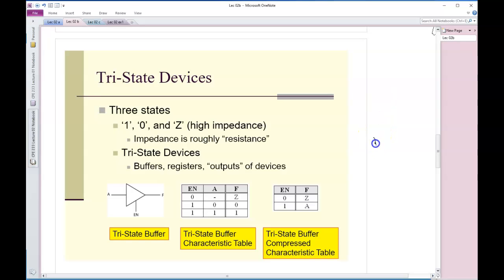So what we have is V equals IR, right? I know people have worked with resistance and impedance probably in your circuits courses, but if I switch this around, R equals V over I. High impedance, the impedance is kind of like the resistance, for lack of a better word. We'll go with that. If it's high impedance, that implies R is large. For a typical digital system, the voltage is fixed. It's not going to change. So if R is large, I is small. This works all the time.